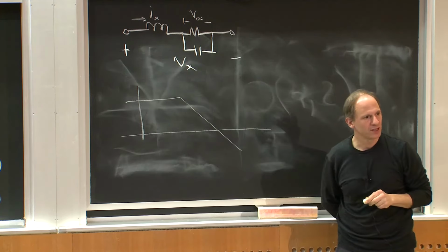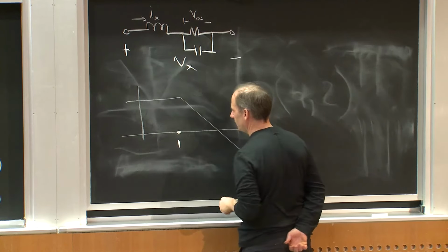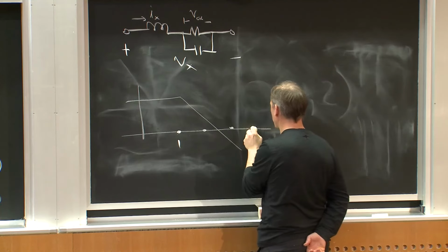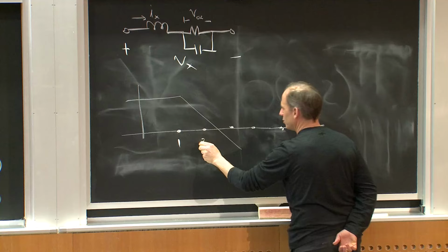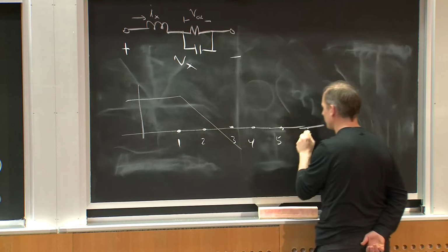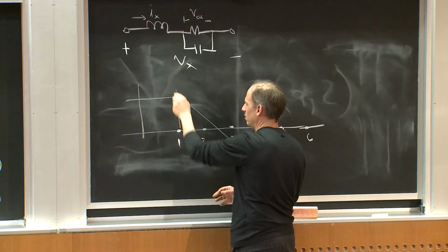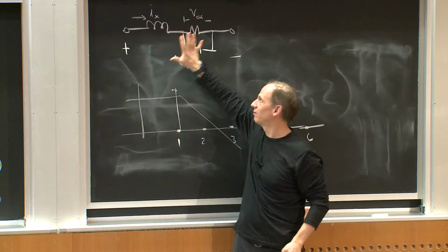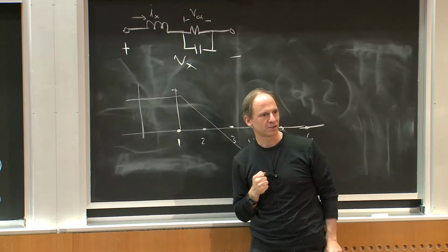Well, what do I generally get? I get a fundamental, then a second harmonic, a third harmonic, a fourth harmonic, a fifth harmonic, and a sixth harmonic, right? So 1, 2, 3, 4, 5, 6. I want to put the fundamental within the cutoff of my filter because I'm trying to get the fundamental to the output. But I want to filter off all the harmonics, right?